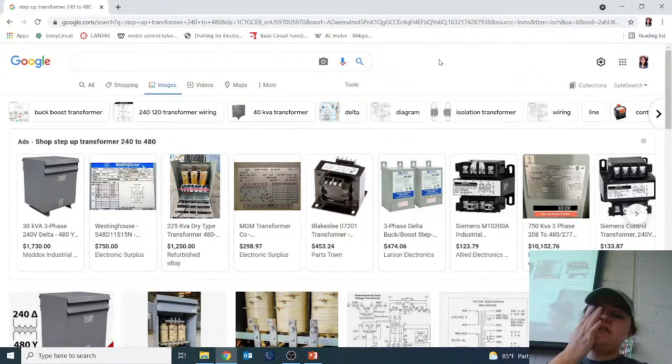Alright, so let's do troubleshooting transformers. After a transformer is installed in a circuit, it may operate without failure for a long time. One reason for this is that transformers have no moving parts. So, if a transformer does fail, it appears either as a short circuit or an open circuit in one of the coils. The two methods that can be used to determine whether a transformer has failed are to measure the input and output voltages and to check the transformer resistance.